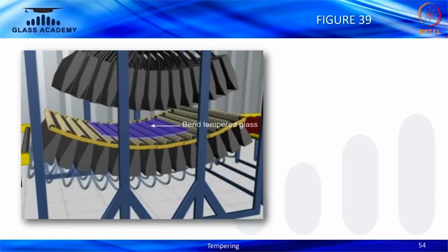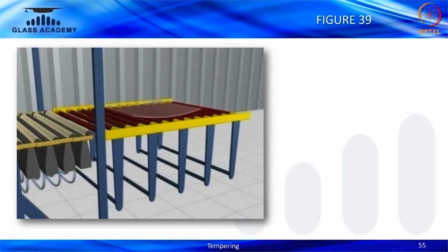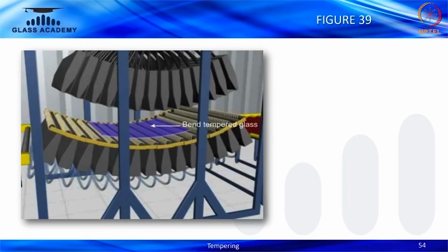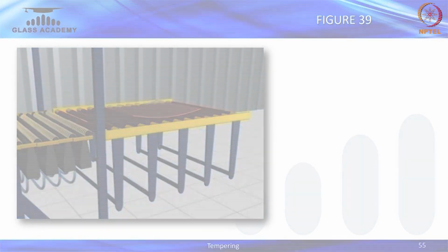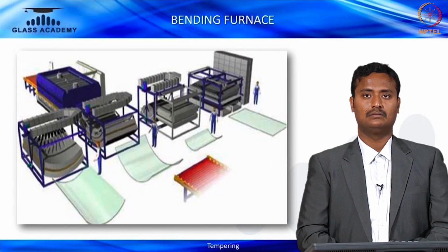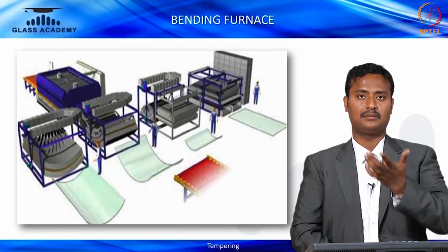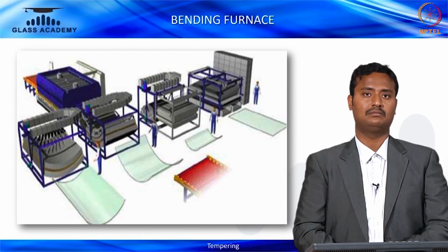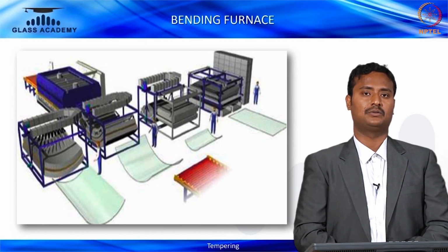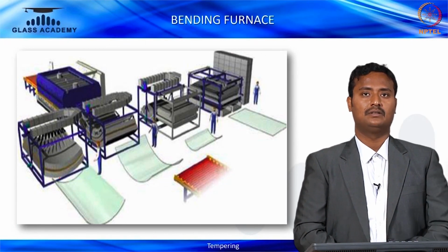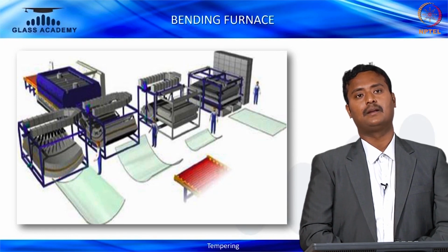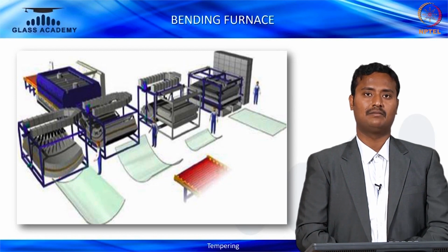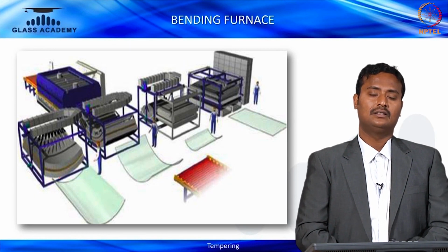You see the bend glass process happening like this. This is a type of convex bend taking place here. It comes out after tempering, and there will be an unloading table. So the flat tempering is what you saw, and the second picture is bend. Different types of bending furnaces were there earlier. This is the tempering furnace schematic diagram, which helps us understand the bending process.